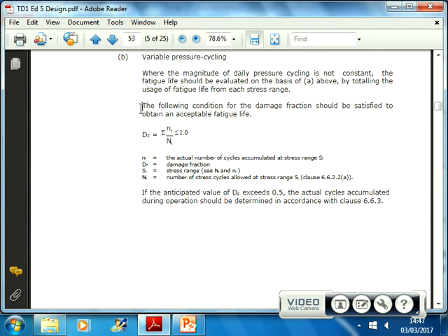By this stage, you will have decided what pressure you're operating at, and you can assume it is going to see some pressure swings, because any operating pipeline is going to see some pressure swings. So if you ended up putting it in the same sort of pressure regime that it's been working in for natural gas, you could say, well, let's assume it's going to see the same sort of cyclic conditions. If you end up saying, actually, it's going to operate at a much lower pressure, because we're going to keep it in the gas phase, you might do a fatigue damage calculation and say it's not going to see any fatigue damage in that. But you've got to do the sums. You've got to do the sums to prove it.